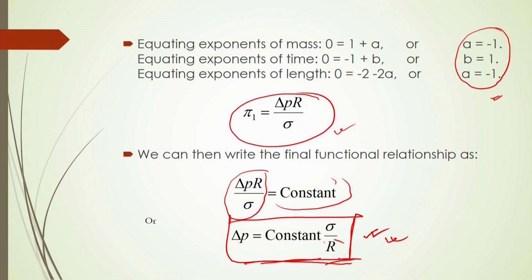If you increase the radius of the bubble, the pressure difference will be reduced, and if you decrease the bubble size, the pressure difference will be higher. So, for small bubbles there will be a higher internal pressure in the bubble. And of course, the surface tension is important. If you increase the surface tension, the pressure will be high.